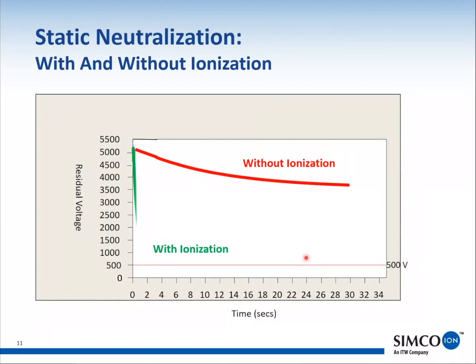If you look at how long a charge will hang around on an insulated material, if you don't provide ionization, this can last a long time. And how long it will last will depend on a lot of factors: the type of plastic material, how insulative it is, what the relative humidity is in the room, the dew point, and how clean that material might be. But with ionization, that's irrelevant. All of those variables, the ionization will take the charge off very quickly. I'm going to show you a video now of how an ionizer will remove the charge.